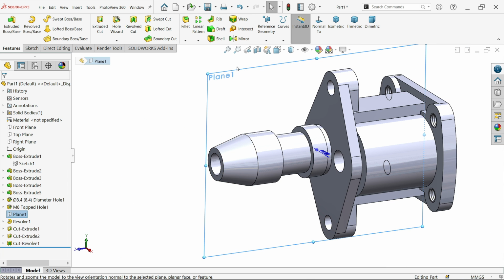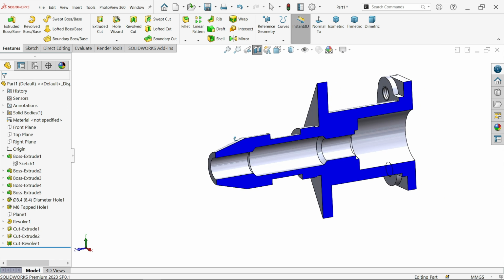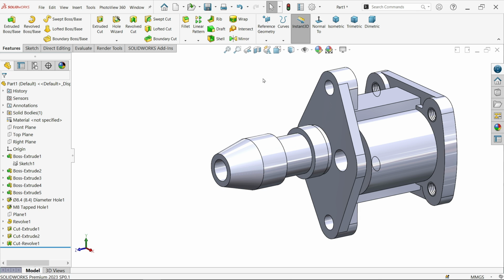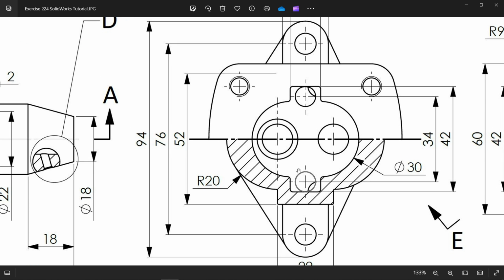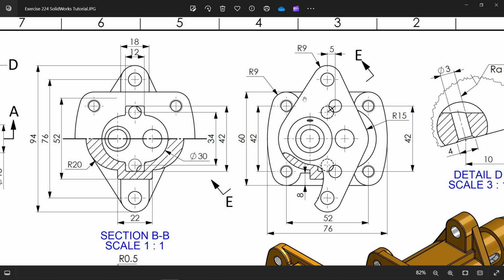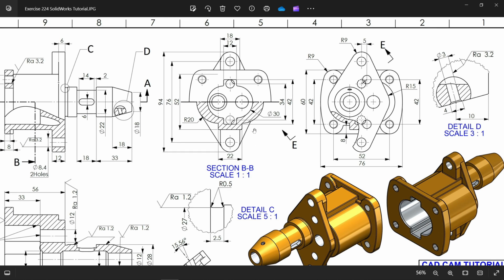Now let's plane one section view. Okay, now look the view. Now what else balance? Now you will see there is a two hole. Now look, this is the front hole, 5 millimeter from here, center distance 42. Okay, then back side, you will see from back side there is an inside hole, center distance 34, and this is lies at center line. So we have to use some lofted cut feature to cut this hole.